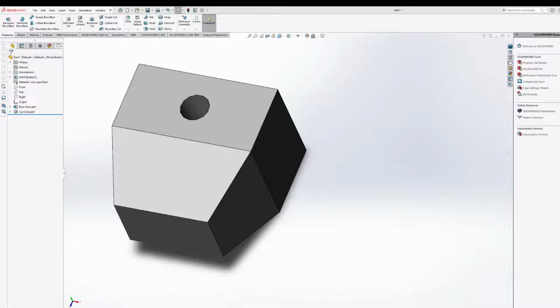But if I do add those things, make sure that you guys are working with those measurements. It's really only a click of a button with regard to the software. The one thing that you guys do need to do is make sure that what you are working with is either inches or millimeters. Because if you start working through this and then you realize, crap, it said 5 inches instead of 5 millimeters, you're going to have to go back and kind of redo some of those measurements because clicking that button doesn't flip those measurements, it flips just how they're referenced.